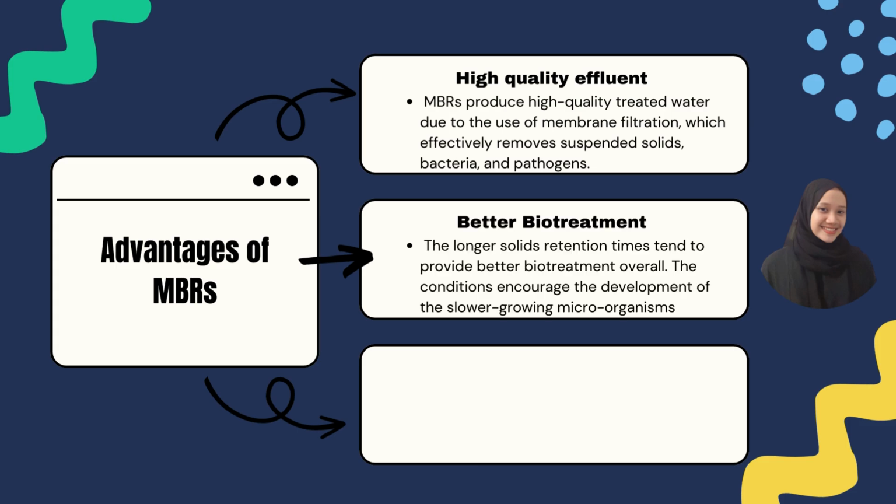Secondly, better biotreatment. The longer solids retention times tend to provide better biotreatment overall. The conditions encourage the development of slower growing microorganisms, specifically nitrifiers. MBRs are especially effective at the biological removal of ammonia.